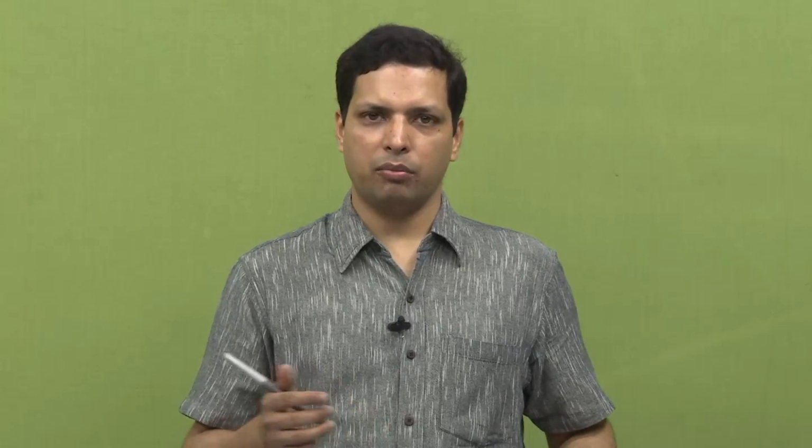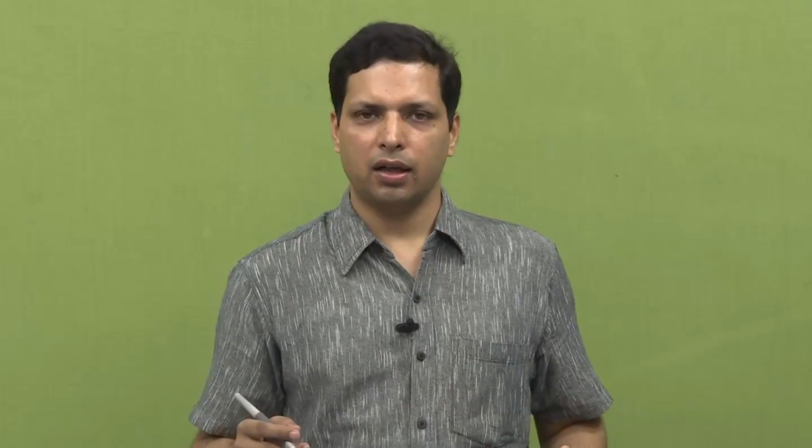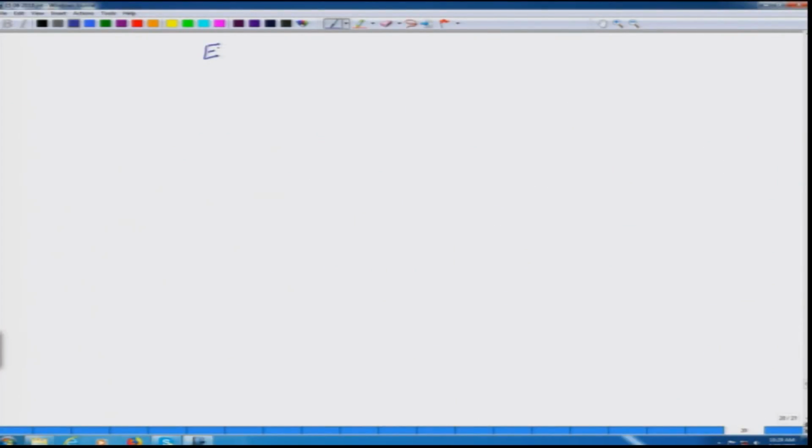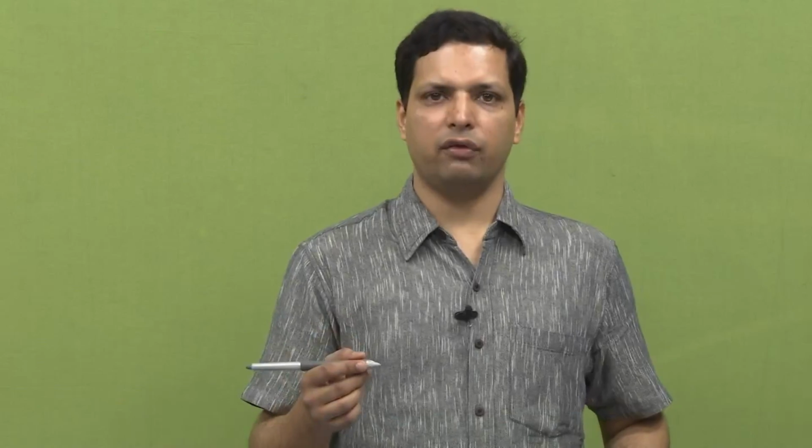We have also looked at the fact that there is mostly nothing called pure edge and pure screw, and it is only mixed dislocation, but we can still understand pure edge and pure screw. So, with that understanding, now we will move on to develop our understanding of the elastic continuum model, which is used to understand energy, stress field, strain field and the energy stored around a dislocation.